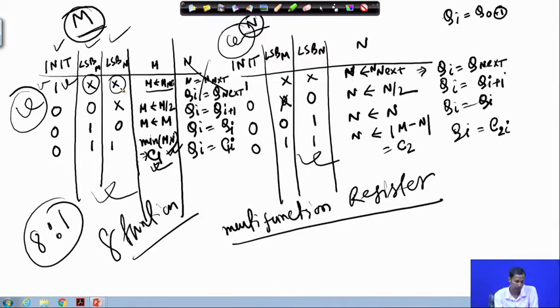So, if I am having these 3 input control signals, at that time I need an 8:1 multiplexer. But I am having only 4 functions to implement. So, why go for this 8:1? Okay. Only I can have this 4:1.